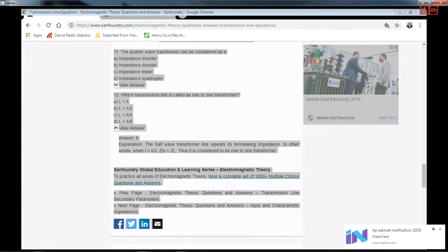So this is how we identify the VSWR, capital gamma, and other things on the transmission line to represent its condition with reference to matching. Whether the line is having any reflections, or whether all the input power is going into the load or not, we can estimate with these values of capital S. This is a very important parameter, and in most institutes or colleges, this S value measurement is an experiment in your final year class.